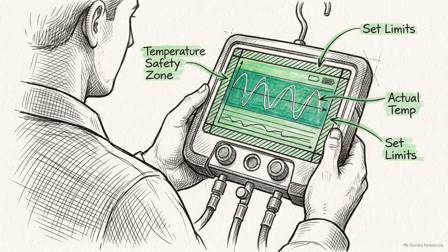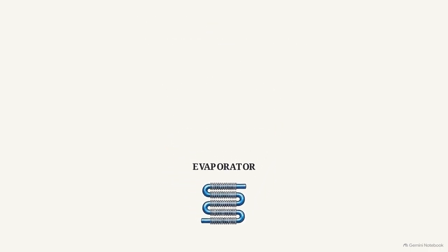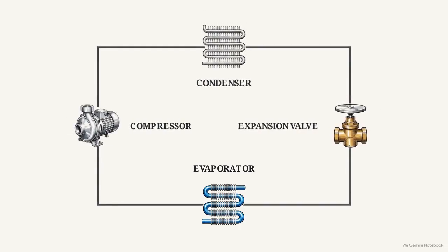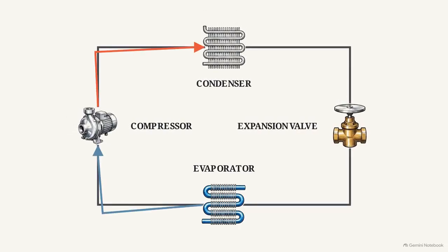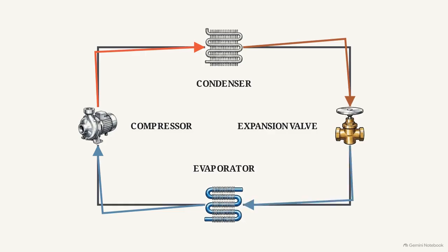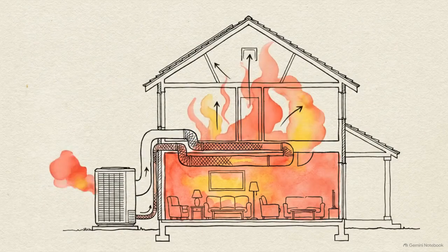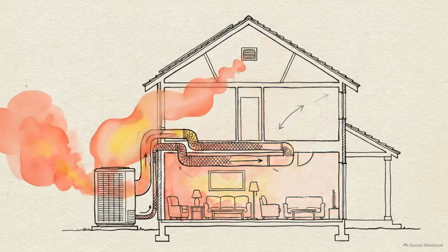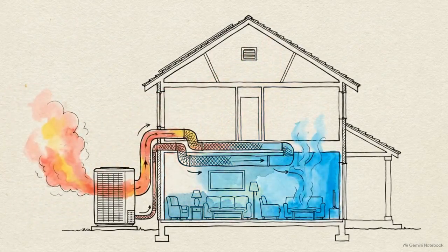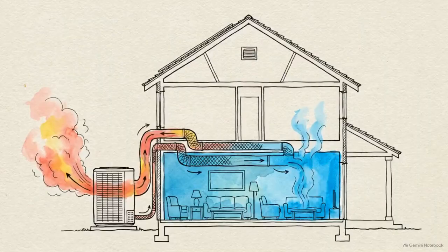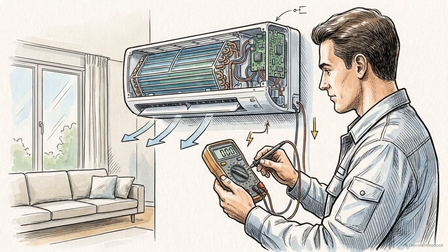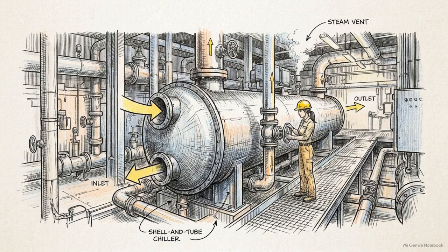the compressor's mechanical survival. When we pull back from the isolated view of the evaporator, these physical rules integrate directly into the full, continuous refrigeration loop. The cycle functions strictly as a mechanism for moving heat from one location to another, driven entirely by the aggressive manipulation of fluid pressure. Whether a technician is servicing a compact direct expansion coil in a residential unit, or an engineer is analyzing a massive flooded shell and tube heat exchanger, the underlying physics remain rigidly identical.